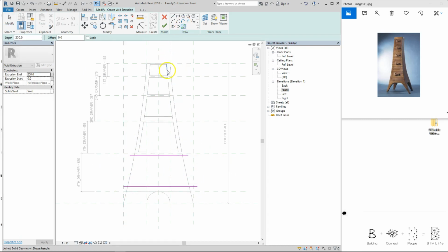Pick lines over here, pick, lock, trim. Okay, so basically the fifth drawer, fourth drawer, third and second drawer, the curvature follows the first one, and you realize that I don't actually pick the curvature from the fourth drawer while I'm doing the fifth one. So I don't want it to have multiple layers of connection or relationship in Revit. I don't want fifth to follow fourth, fourth to follow third, third to follow second. This will be more complicated.